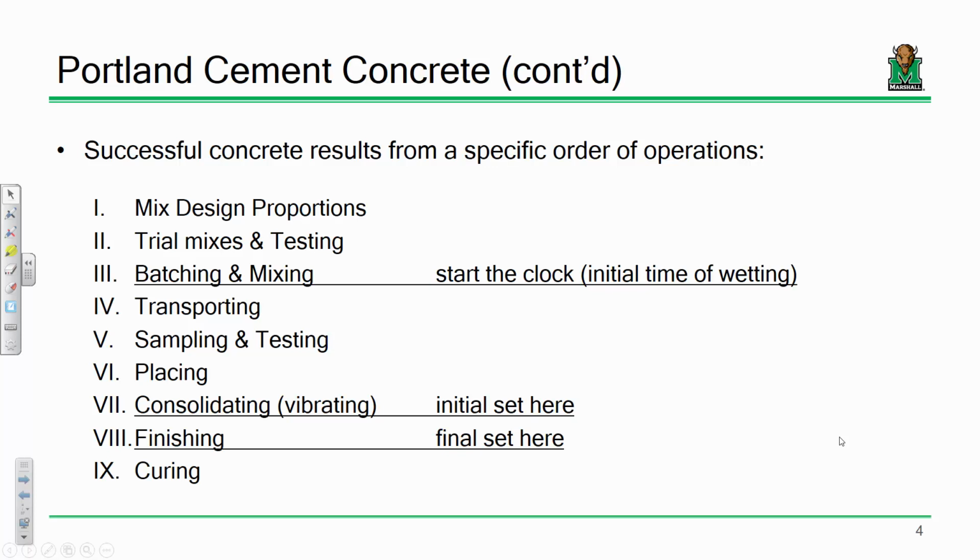But if you're using regular concrete, for instance, if you're casting a bridge deck, you'll see construction workers with these vibrators, a long metal shaft, and you stick that in, and it vibrates, and it gets the concrete to fill in all those voids and spaces. And we've got to do that appropriately. Finish the surfaces, prepare it for curing, and then there you go.